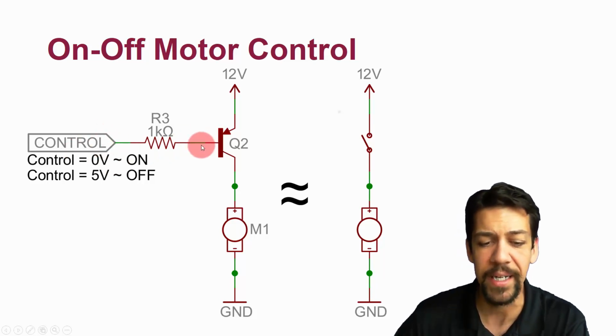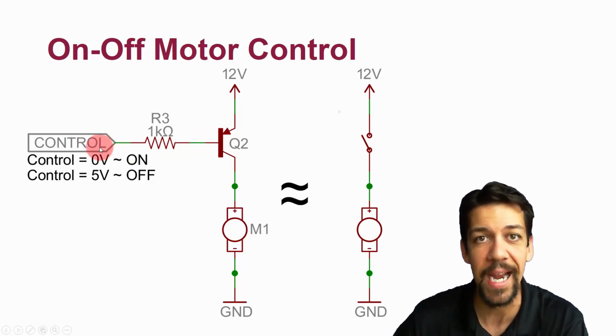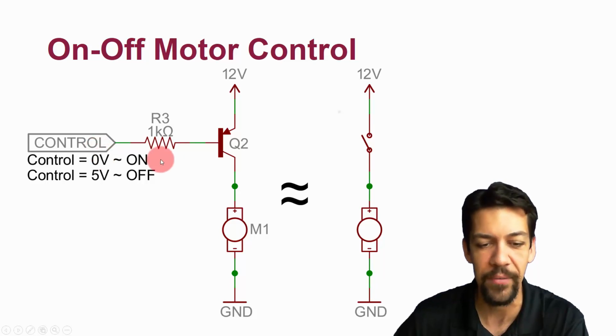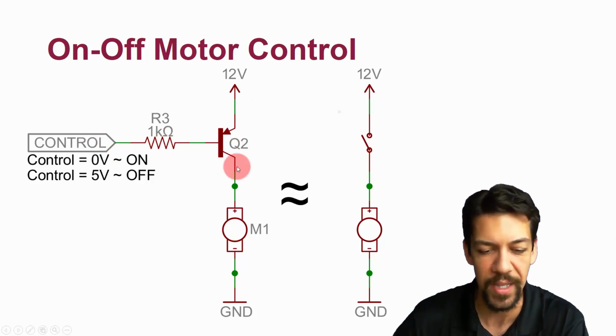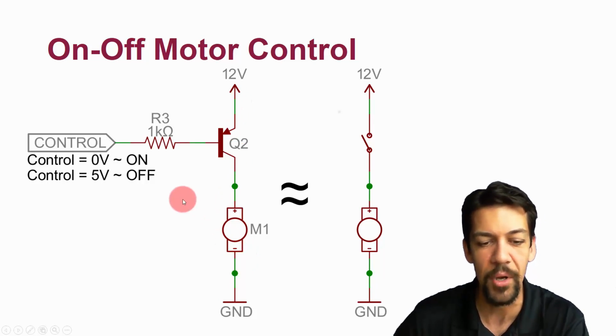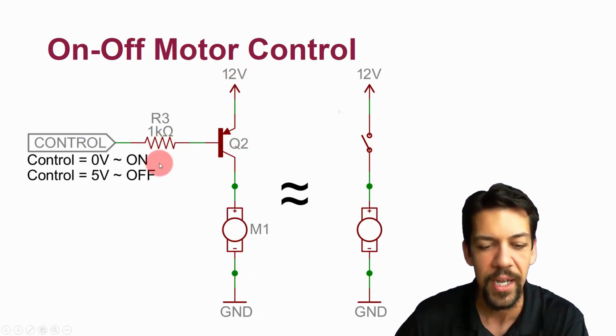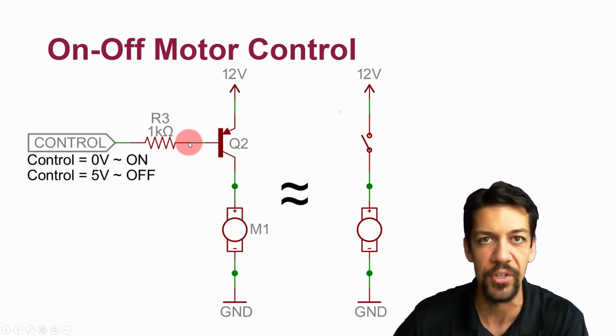And in this case, we're doing an active low behavior, right? So when we drive this to 0, that drops down the base, which allows current to flow into the motor. And the reason why we're doing active low is because if we were doing active high and put it on the other end, we would need to overcome the supply voltage to get the transistor to open.